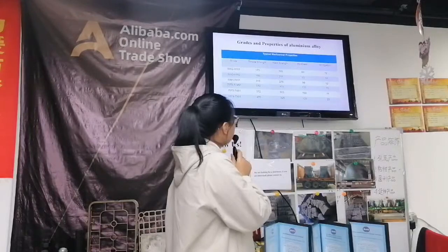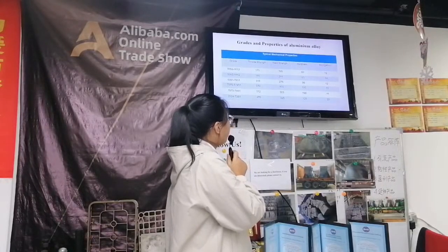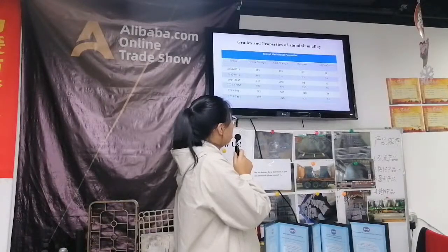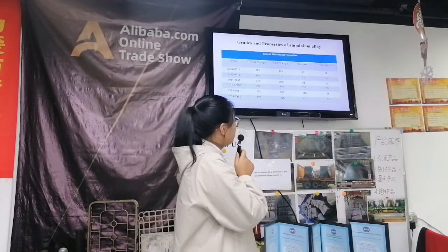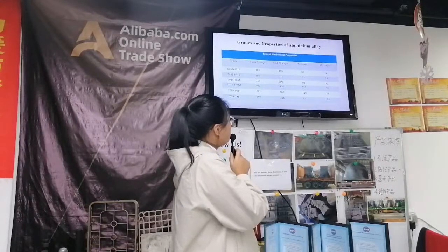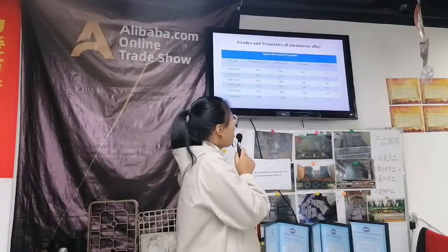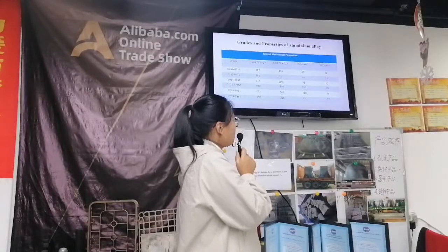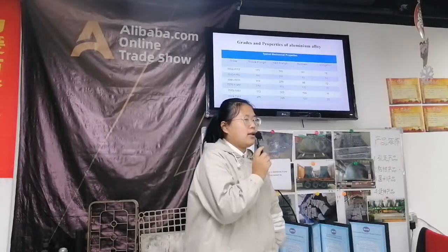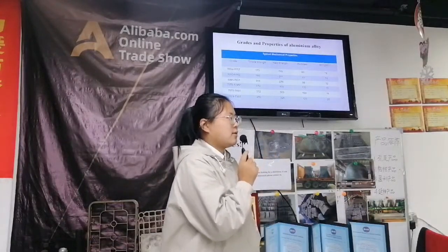For grade 7075, for tensile stress is 572. For yield stress is 503. For hardness is 150, and the elongation is 11.